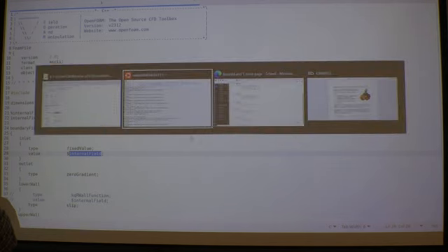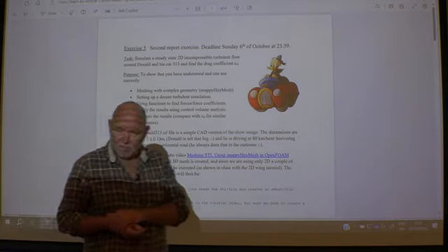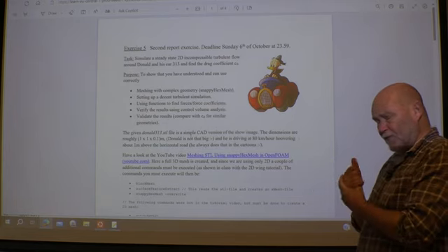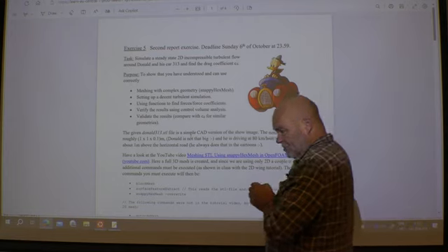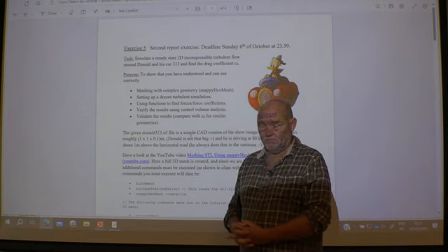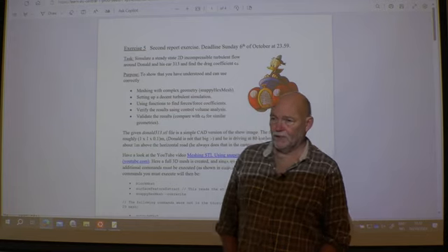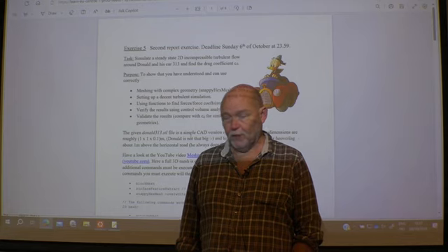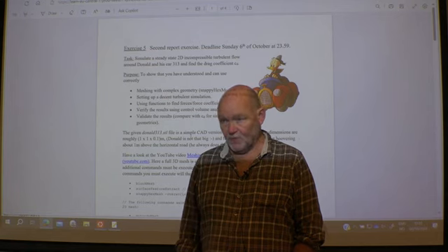Okay, any questions to then the exercise? Yep. When running SnappyHexMesh, how long should it take before the mesh is complete? It depends on how refined you want the mesh. If you are ambitious and you want a really detailed mesh, this is going to take forever. So hours. And something we are going to look at today is to run it in parallel. SnappyHexMesh can be run in parallel, so that can make things much, much faster. But you have to be prepared. It takes a long time if you do it too detailed.